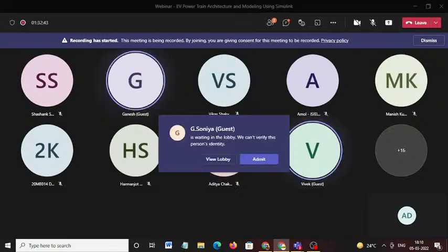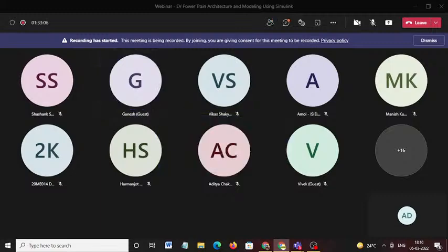If I am releasing the throttle and it is not coming back to its original position, the signal reaching the ECU is not proper, then there will be an issue. It can be pointed out on the controls. This is one of the issues I have seen recently in the present vehicle.